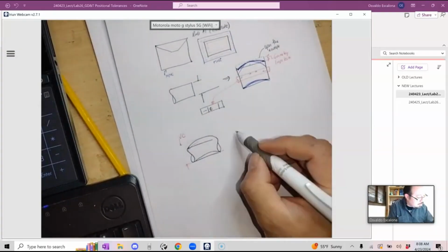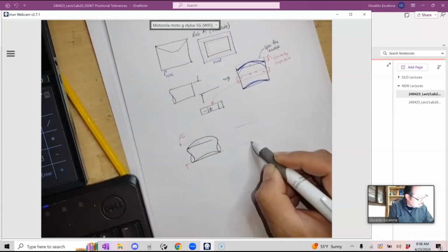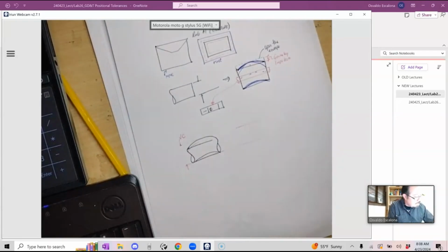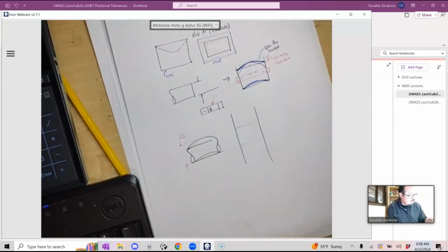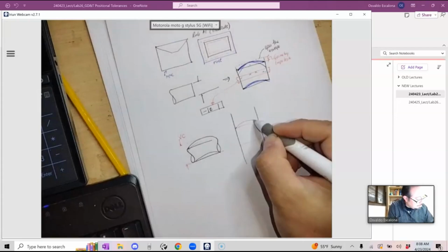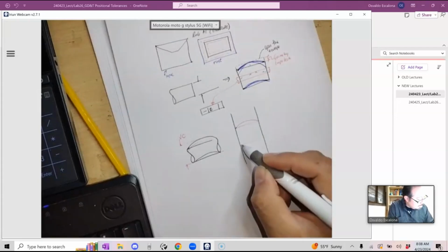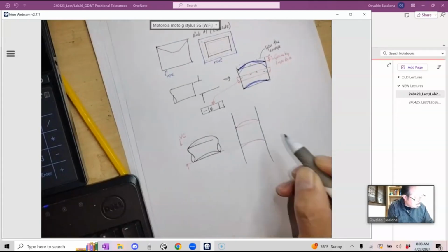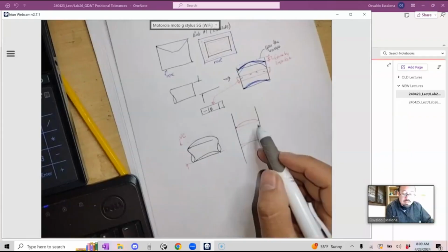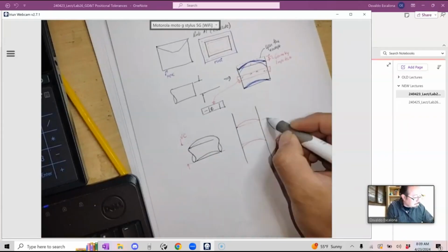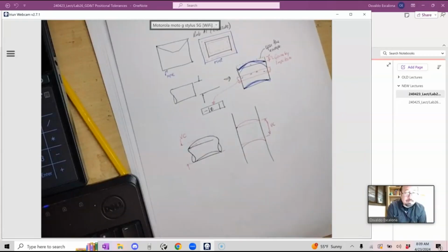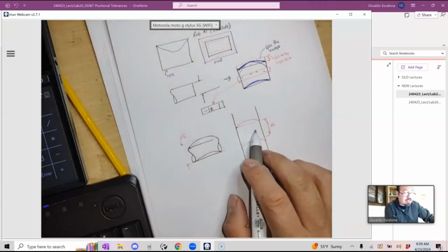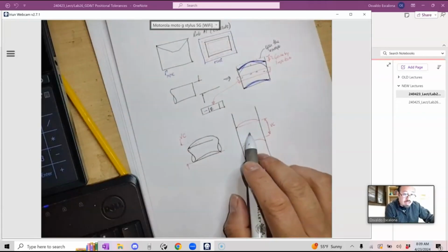I can also grab my hole and do the same concept. Let's say I got a hole that was big, then it was small, and then I made it even smaller than it was before, because once I have a hole and any imperfection, the hole actually acts smaller than what it actually is.